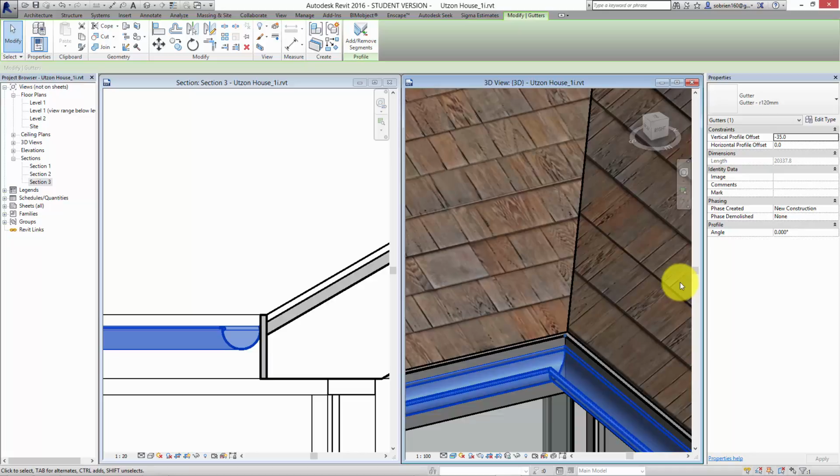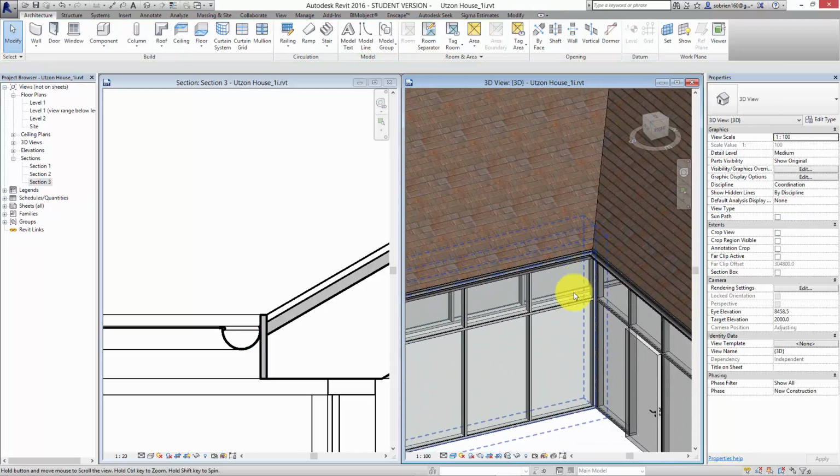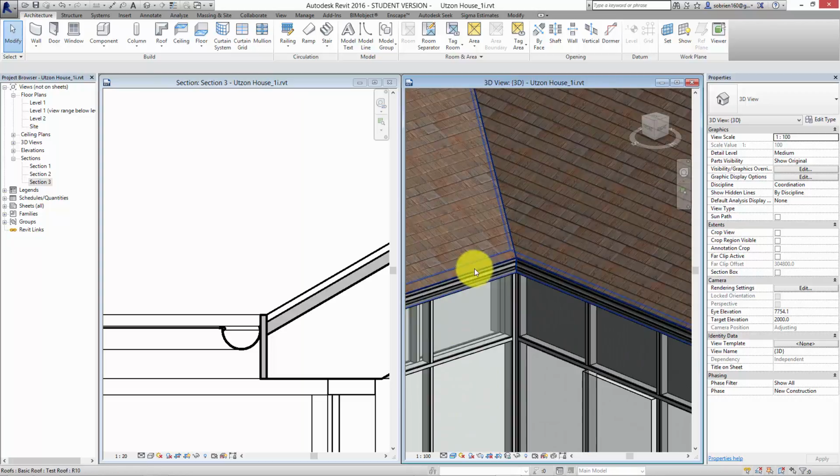As you go further in it, you just add things using 2D annotations. So a good rule of thumb when you're dealing with Revit is if you can see it from the outside, or if you can see it in detail, that's as much work as you need to do in 3D modeling.